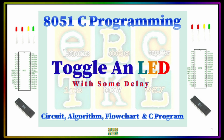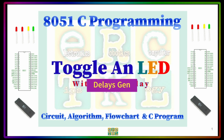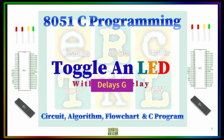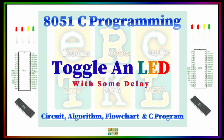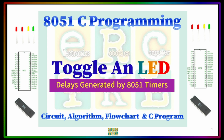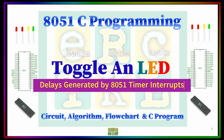In this video, we will be talking about 8051 C programming, and the problem is about toggling or blinking one LED using different techniques. The first technique is using some sort of a delay with the use of for loop commands. The second technique is by using a user-defined delay like MS delay. The third one will be talking about the timer delay, and the last one will be using an interrupt to generate the delay. Let's start with the first one.